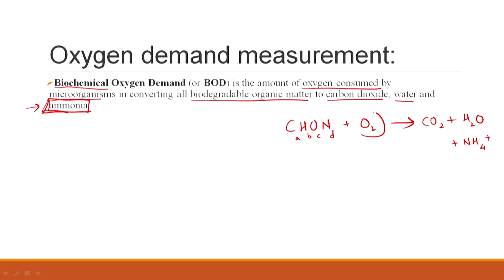Thus for this reaction the amount of oxygen required, that is your biochemical oxygen demand, but only if the compound is biodegradable, or only if the microbes can degrade it, let us say aerobically. So, that is the one that is called biochemical oxygen demand.